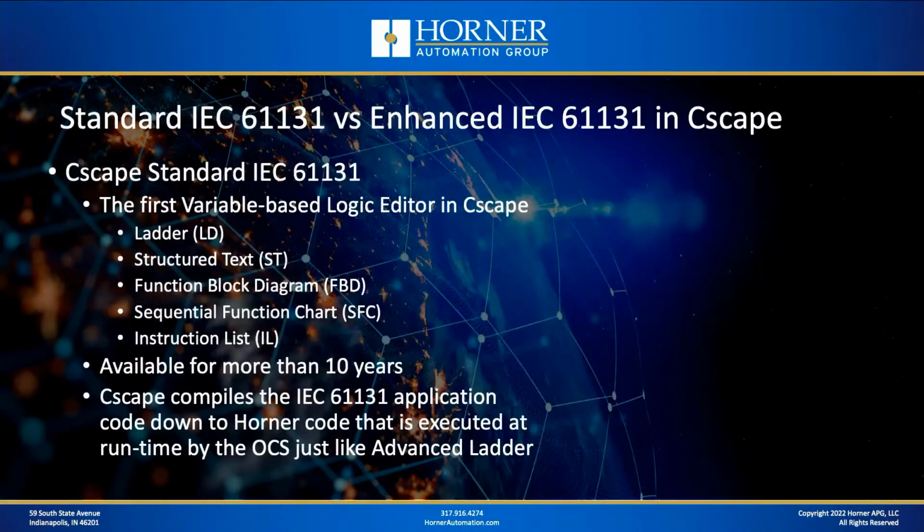Now we're going to compare the difference between Standard IEC and Enhanced IEC, and we'll start with Standard IEC. Standard IEC was the first variable-based logic editor in Cscape. It predates variable-based advanced ladder. Like every other IEC package, it offers the 5 languages of ladder, structured text, etc. And it's been available for more than 10 years, and it's a very popular option today.